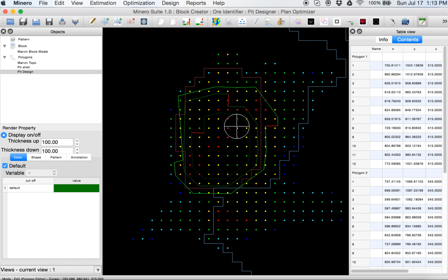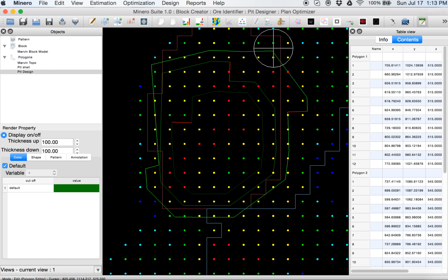We can always edit this shape. Let's say we wanted to have a switchback here because we want to take advantage of the north area. We can edit. I don't know what happened with this point. We'll check it out later. Move this point. I can use offset tools to do this anyway. I can create my switchback here.